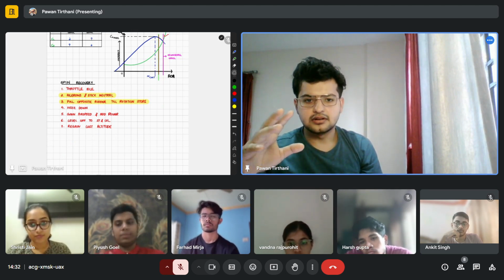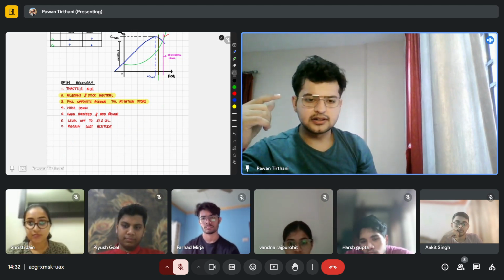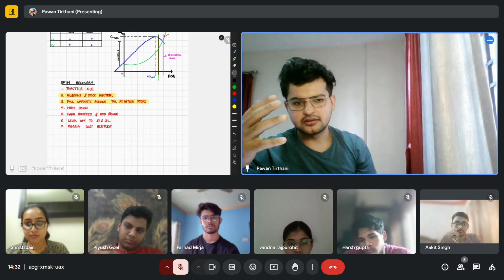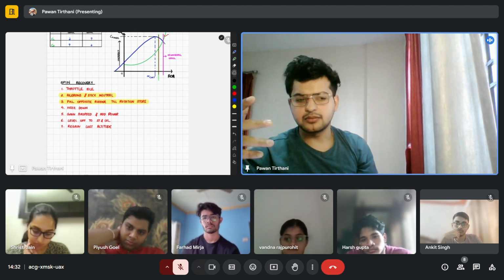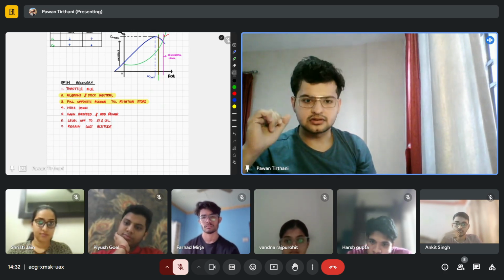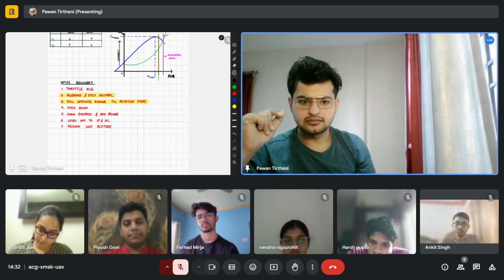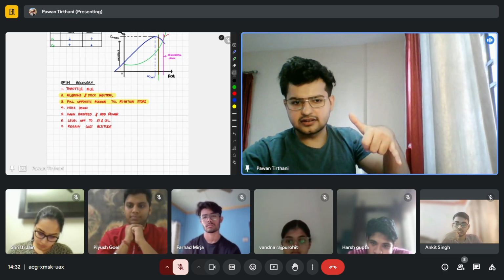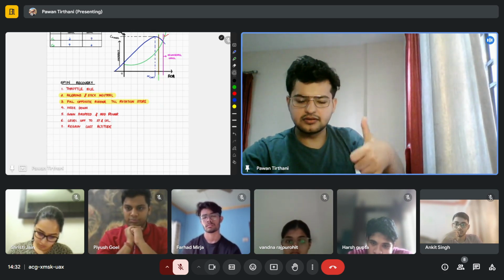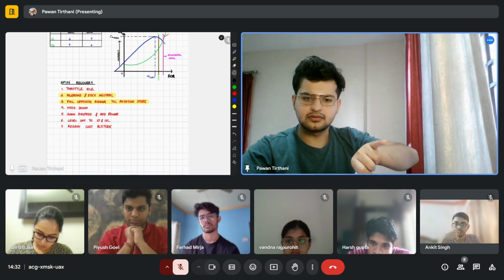ठीक है. अगर तुम्हारा डिसोरिएंटेशन हो गया एंड यू डोंट नो विच साइड टू प्रेस, हो जाता है ना. जब आप स्पिन में जाते हो, इट्स अ वेरी ओवरवेलमिंग मैनूवर. यू फॉरगेट विच साइड द एयरक्राफ्ट एक्चुअली ड्रॉप्ड इन द हीट ऑफ द मोमेंट. लुक एट द टर्न कोऑर्डिनेटर. उसमें विंग ऐसे रहेगा या ऐसे रहेगा. अगर वो ऐसे राइट रडर प्रेस करो, ऐसे लेफ्ट रडर प्रेस करो.